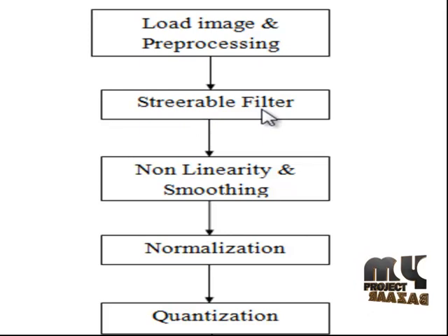The descriptions for all local structures of an image are realized by using a set of oriented second derivatives of Gaussian-like filters. An important thing is that these steerable filters we used are XY separable, which helps to obtain the filter responses more efficiently. The second derivative of Gaussian filter is a bandpass one and is often used for image analysis. It can be rotated to an arbitrary orientation by linear combination of the basis filters, which has been used in motion, texture and orientation analysis.